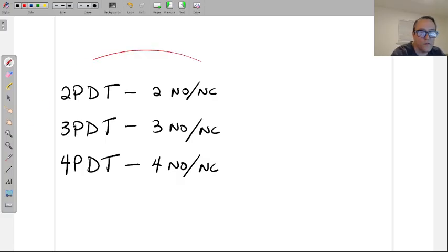All right, so this is one of the ways that you will order your control relay. Again, we're back to me just calling the supply house. I need a control relay. Again, first question is, what is the voltage to the coil that you require? I will say the voltage to the coil required, and then the next question is, how many contacts do you need? So I'll tell them, I need a 2-pole double throw, a 3-pole double throw, or a 4-pole double throw. Now, the other way that this gets explained on the relay, and we're going off book here now, the rest of the stuff here in the book, I'll come back to it for a second, but unnecessary to continue. I just need the relay.